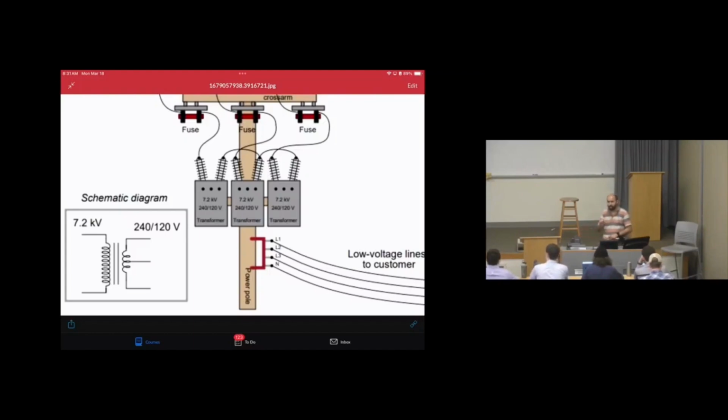Then a small percentage of unbalance can be allowed, up to 3%. Sometimes it can be violated up to 5%. If there is more than 5% unbalance between these, then we need to take action. So we can make some studies and say maybe phase C has lower loads than the others, then we can connect an additional home to maintain the balance. So again, overall, to overcome some problems that we have in the power utility, we are trying our best to make it as balanced as possible.